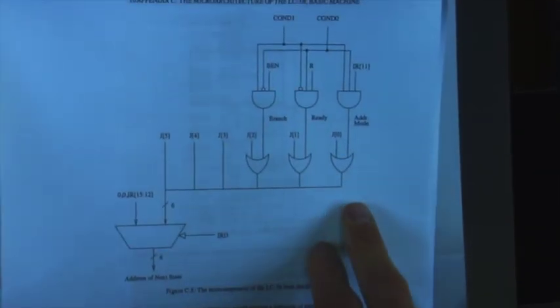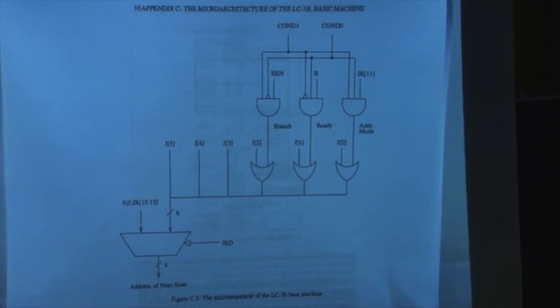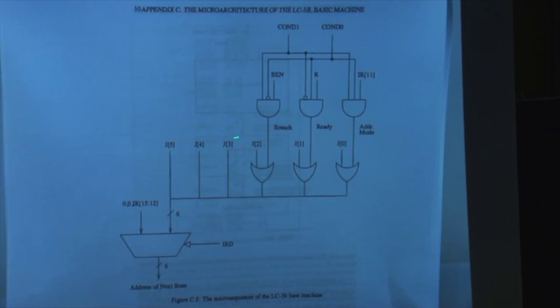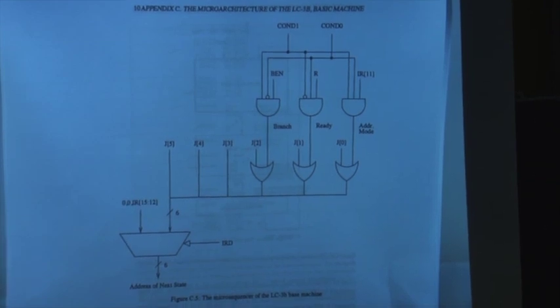Let's just take a look at that in the microsequencer. I'll have to find the microsequencer first. Okay, there is your microsequencer. Basically, that state, when the add instruction finishes, the next state is state 18. How do you encode state 18? Well, these J bits tell you what is your next state. So you unconditionally go to what is specified by these J bits, which are set to 18 in that particular state.